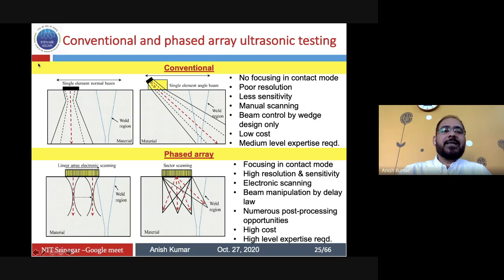And that is exactly what is happening in the case of the transducer, where every point acts as a transmitter. But beyond a certain point, that is, beyond the near field, it starts propagating like one wave front, which is diverging, and then slowly the amplitude goes on decreasing with the divergence.